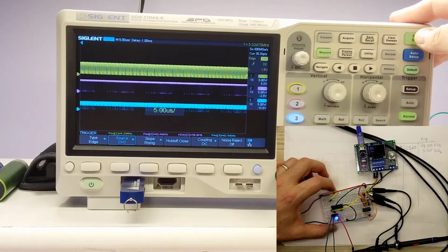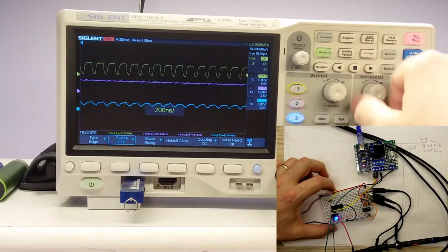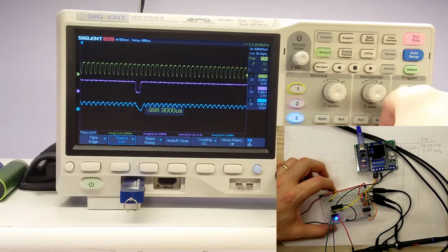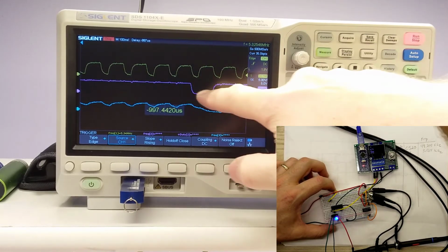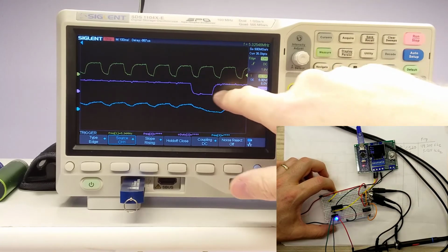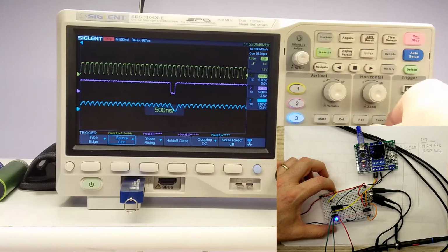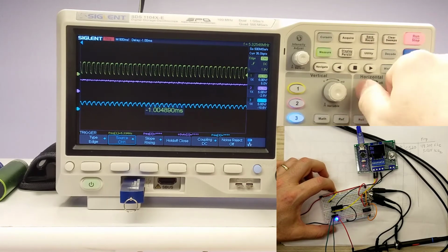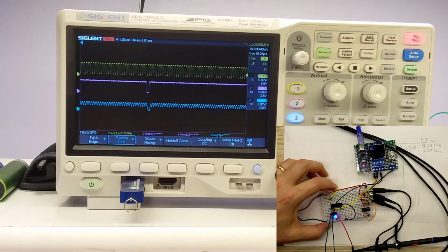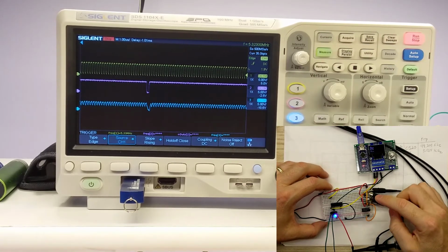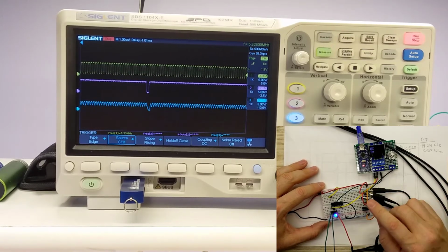So here we're running at about 5.3 megahertz on the first channel. Let's go ahead and pause that and we can zoom in and take a look at it. Now let's look at this little peak here because it seems to be pretty consistent. And so you can see that second channel went low for a cycle, and you can see the output followed along just fine. So even up at 5.3 megahertz, this appears to be keeping up just fine. So there you have it. I'm going to say that the AND gate is successfully running easily at 5 megahertz without any significant problems.